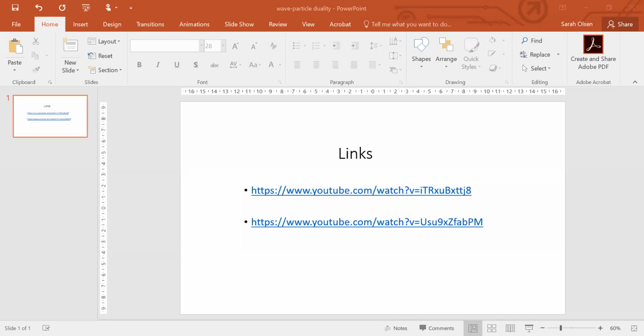If you remember, the closer the Fermi position is to the conduction band, it's suggesting the more n-type the material will be, and therefore the higher the carrier concentration of electrons in the conduction band. And so the equation that you need to look out for is n equals N_C e to the minus (E_F minus E_C) over k_B T, where k_B is the Boltzmann constant and T is temperature. So hopefully you can see that.